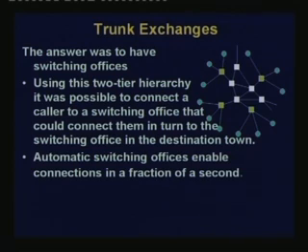So, we came to the so called trunk exchanges. Now, what are trunk exchanges? Well, there are local exchanges, and if one local exchange wants to go through to another local exchange, it usually goes through a trunk exchange. So, this is a two tier hierarchy. There will be some trunk exchanges, and each of the trunk exchanges would be connected to a number of local exchanges, and the trunk exchanges among themselves would be connected in some fashion.